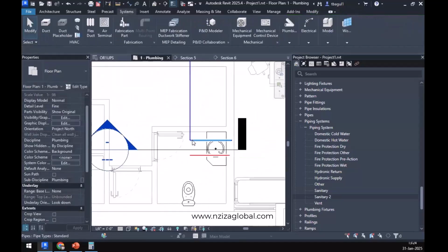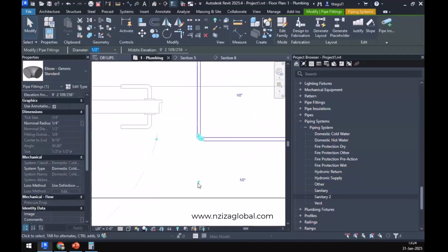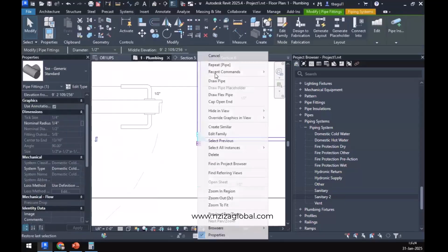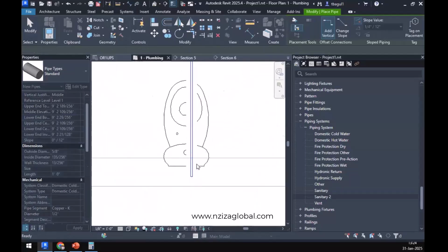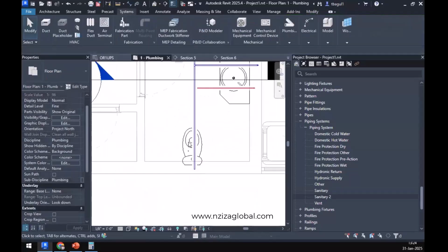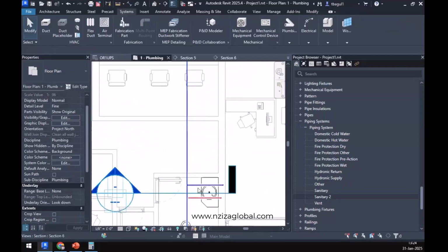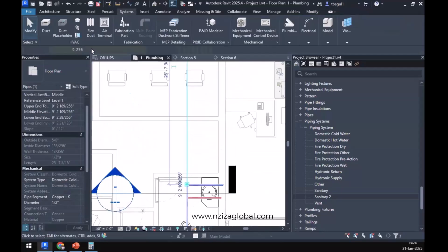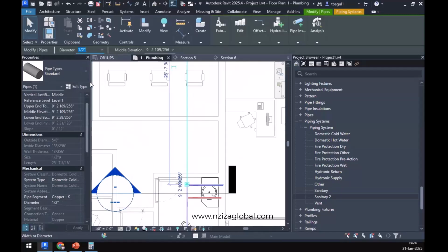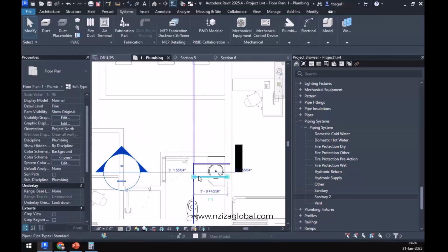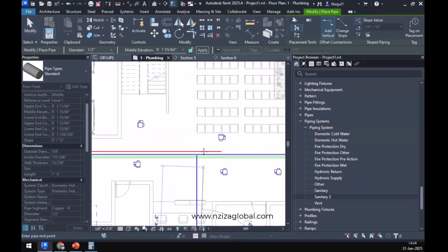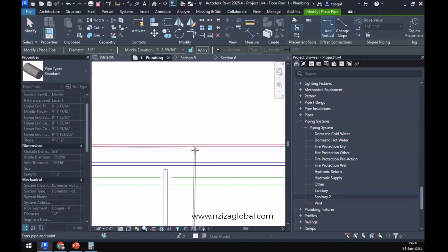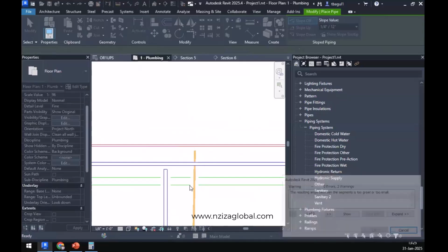Before doing that, we'll also make sure that we have a T for the water closet, right? Because that one also requires a cold water line. And we had seen 5 plus 1.5, we need to be at 1 and 1/4 inch size over here, right? But this one will stay as is, right? And then we can bring up this one to this one. We'll not connect it. We'll make sure that we have it properly coordinated.